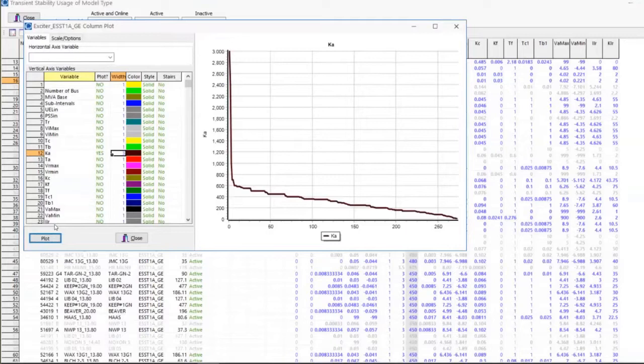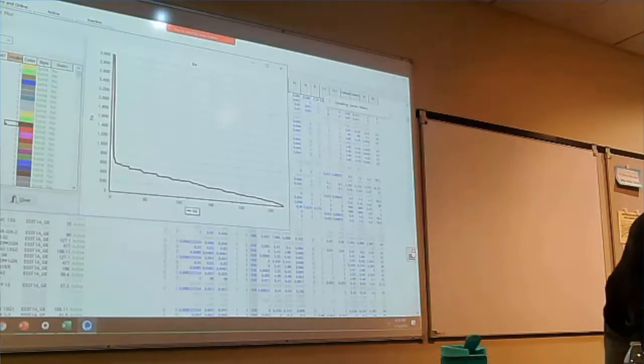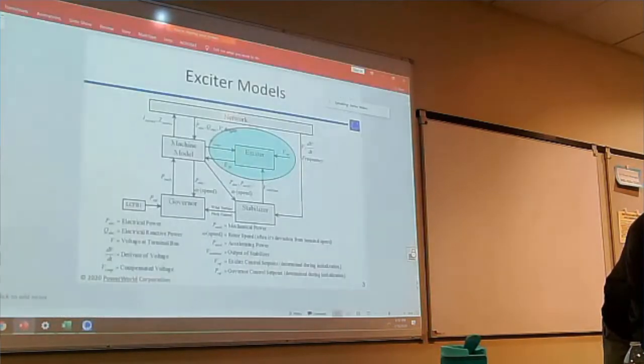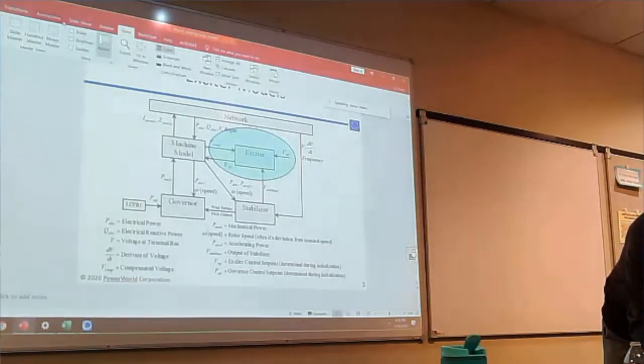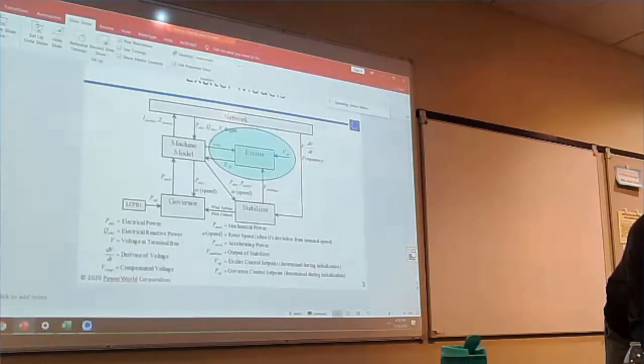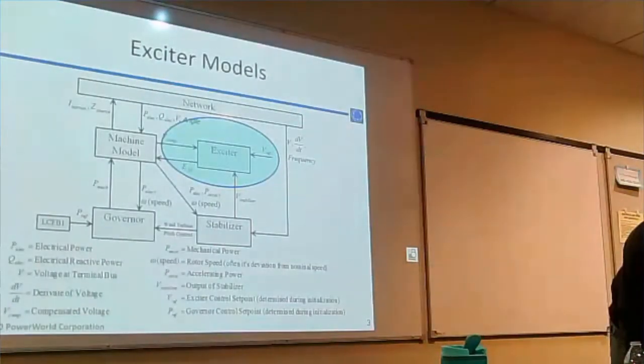If I was having trouble and it was associated with a generator, or the exciter, that had a gain of 3,000, I might suspect that gain. 3,000 seems like a pretty high gain there. It's really hard. The nice thing in PowerFlow is if somebody puts in a limit of 10,000 millivolts, every engineer knows that means we have no idea what the limit is. But the gains that Tom's going to talk about, there really isn't that kind of intuition. It's harder.